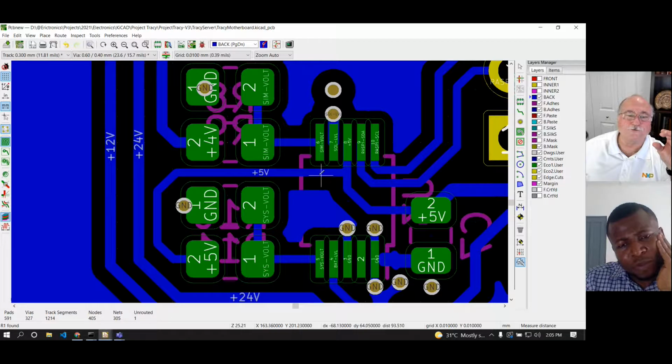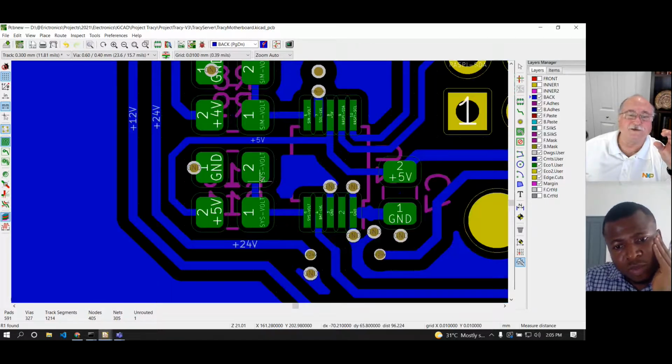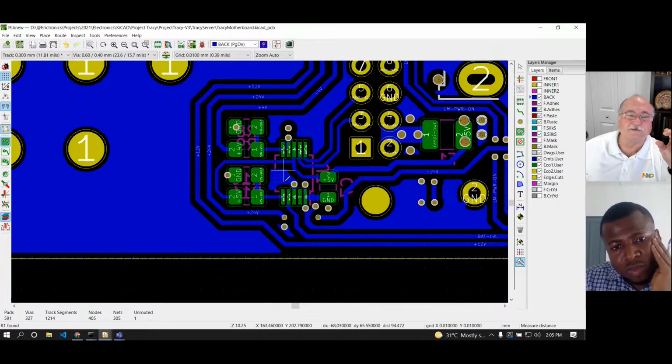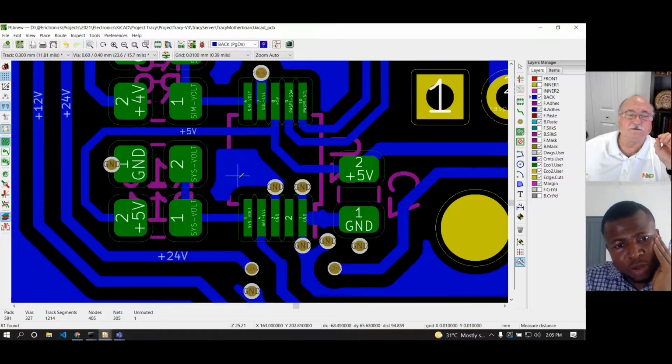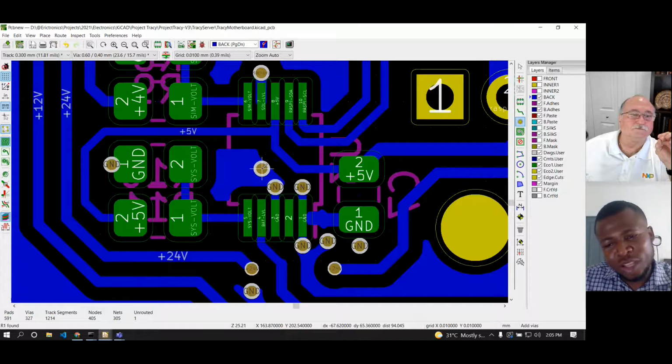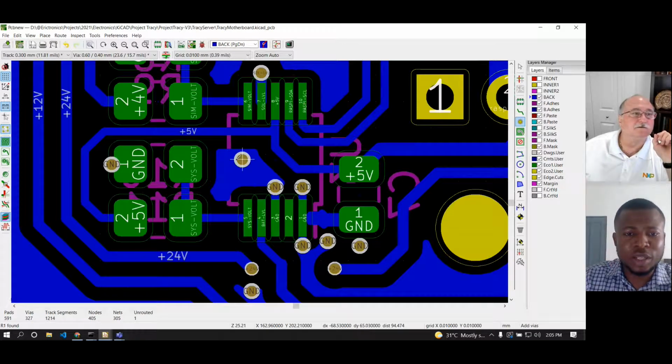And below your cursor is another example of a piece of flood that needs to have another ground tacked into it. This one. But it's under an IC. ICs are exempted from the components that shouldn't have flood under them. Right, but you've got an isolated piece of copper, so either find a way to put a via in there or just delete it. All right, then I think I can put a via here.